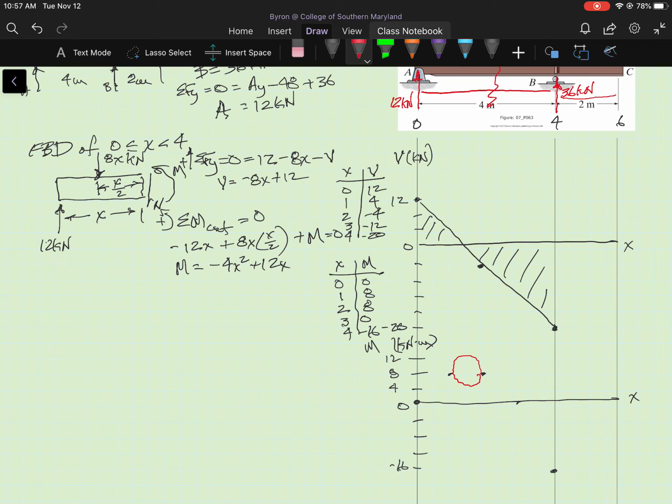You should remember that from previous algebra. If the slope of the moment curve is 0, then the shear must also be 0. Okay, so that's lining up, because if we look above that point at the shear curve, we see that the shear curve equals 0 in that general vicinity.